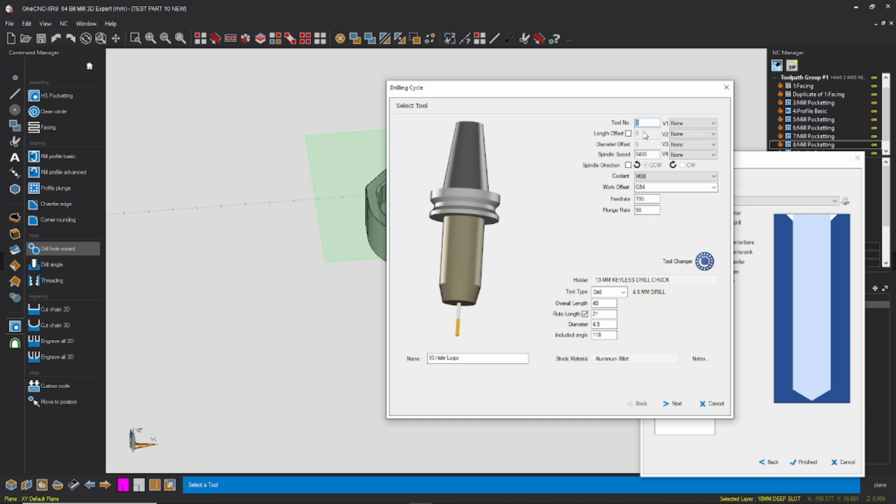So what is it? We're tool 6. So I do 318 times 50. Gives me 15,900, and then I divide that by my drill diameter. So divide by 4.5. That's my speed. That's aluminium speeds and feeds, by the way. And then I will get